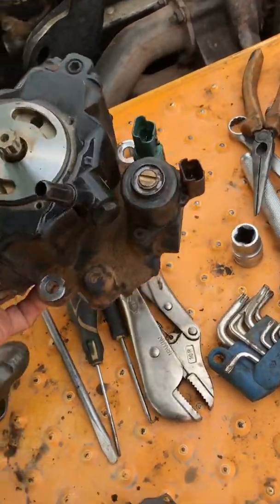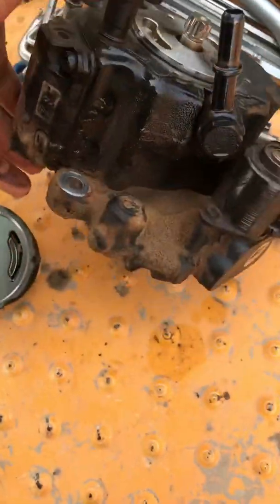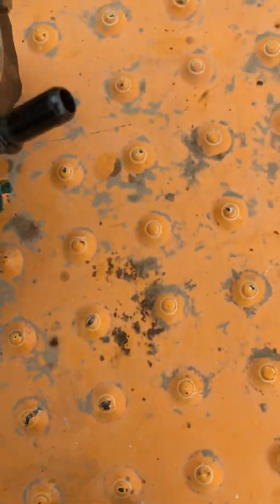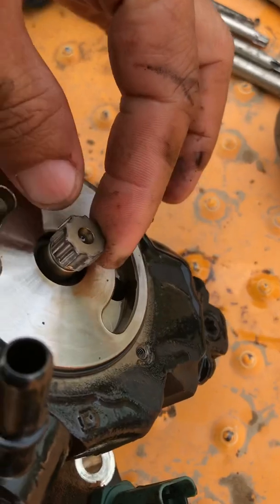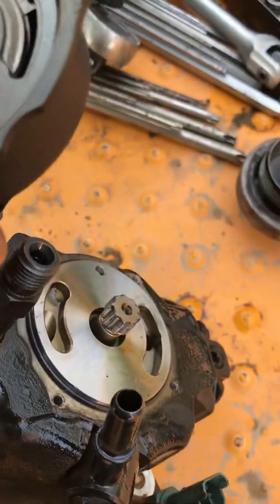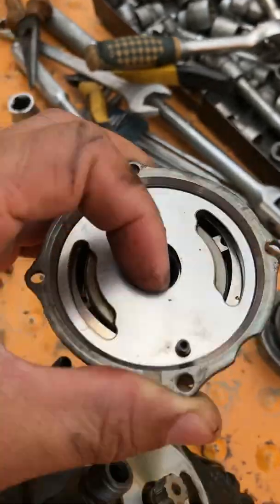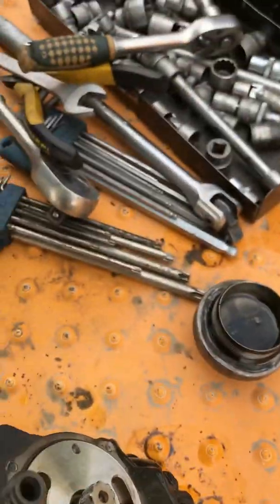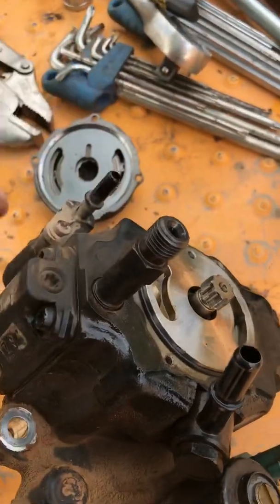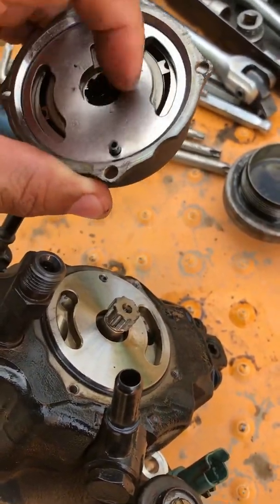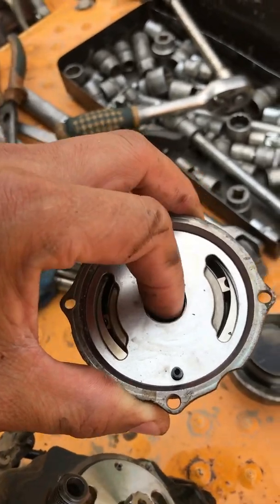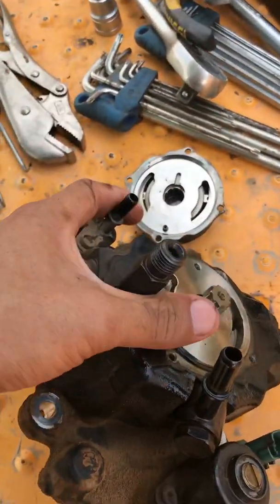So I already took out the pump. This is the pump. Look at the supply shaft here. It's not too damaged. There is damage, but not too much. The damage is in here, not the shaft and not the male or the female. That means when the pump is rotating, it slips here, so it cannot turn the transfer pump side, so that's why the engine cannot start. So the issue is the pump.